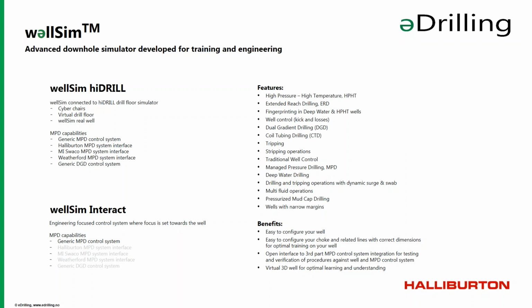Then you have the WellSim Interact, which is the engineering-focused downhole simulator, where the focus is moved away from the drill floor and all the machinery, and is more on what's happening in the well. There we have a generic MPD control system as well, but we are also looking into possibilities to interface the different MPD providers' systems. It can be very suitable to train up new engineers in the MPD company, or engineers involved in MPD operations in general.